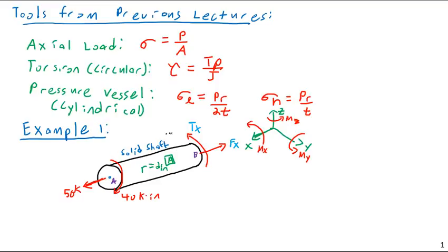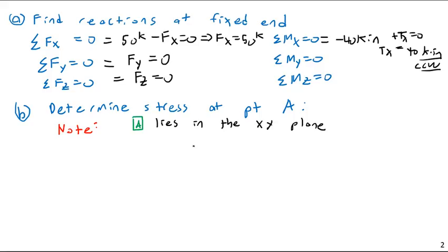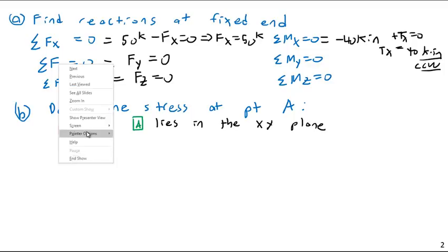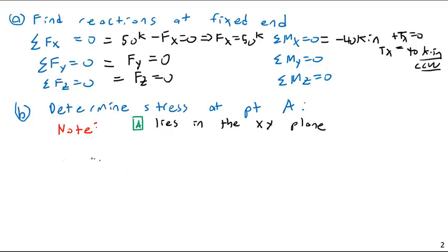The reason for that is because we're going to have a combination of torsion and axial force. So that doesn't have anything to do with how it was drawn. That just has to do with the loadings. All right. Now let's look at the axial. Let's look at the different loadings we're going to have. Let's first get the axial stress, or the stress caused by the axial load.